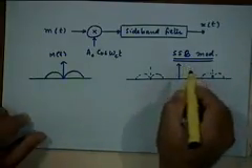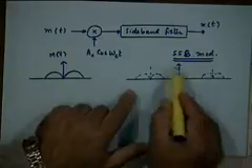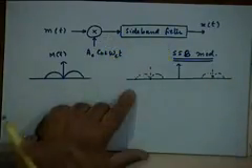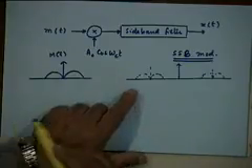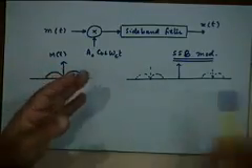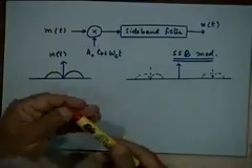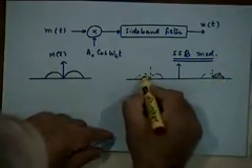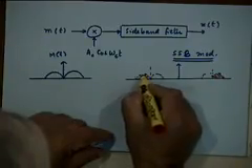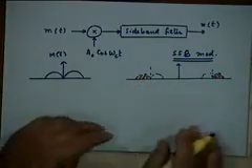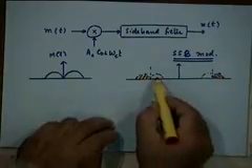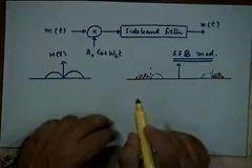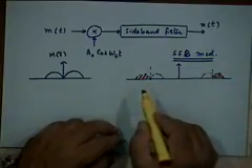This would have been the spectrum of the double sideband signal that is coming here. Now after you put the sideband filter, what are you retaining? You are retaining either this part or you are retaining the other part, right?